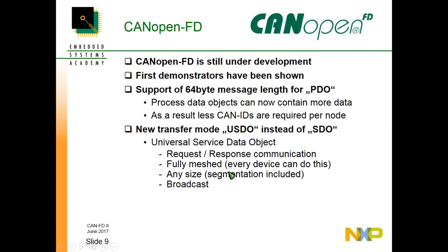And also something new we introduced in this mode is a broadcast mode. So these requests, when you're doing a write, they can actually be a broadcast to everyone. So you could, for instance, in one message inform everyone out there who you are and send your identification as a broadcast. Or at the high end, what we have done in a demonstrator is a firmware broadcast. We'll come back to bootloaders later, but literally we implemented that one host is sending new firmware to multiple devices in parallel at the same time as a broadcast.